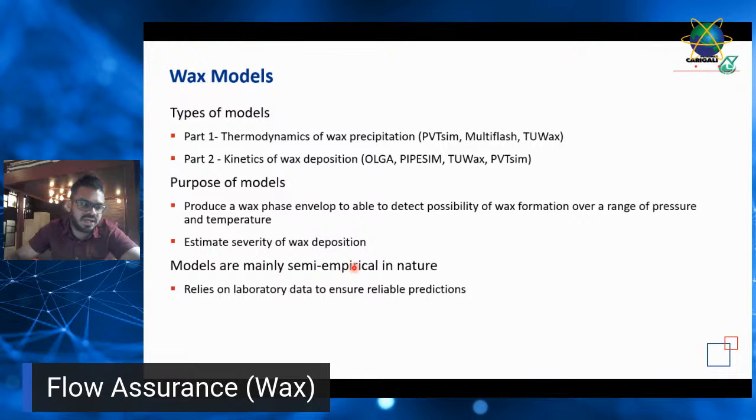Unlike hydrates, which are quite well known because the hydrate model has already been validated against multiple experimental data, wax modeling in terms of prediction highly depends on the waxy nature of your crude.